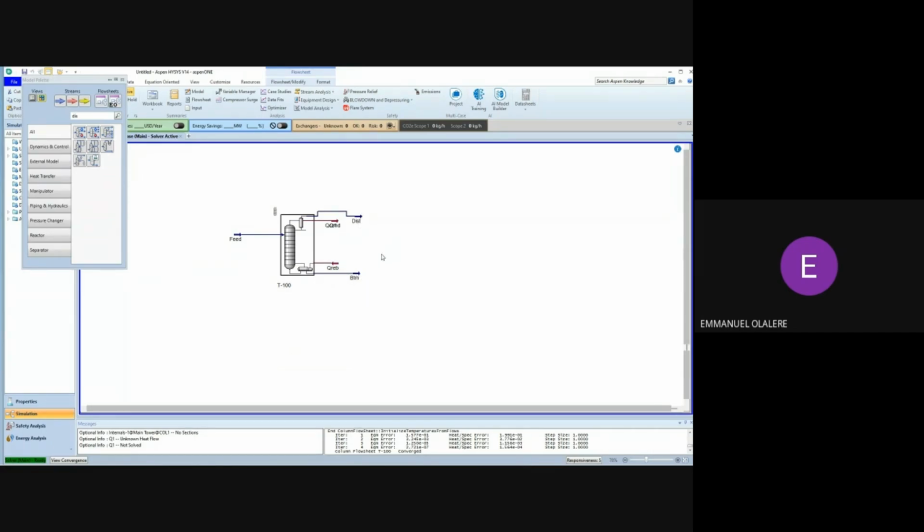So let's say the process is naturally being supplied at 225 degrees Celsius and 250 psi. So I'm assuming that I can't manipulate this. If I can't manipulate the feed, then another thing I can manipulate is the reflux ratio. Now, if I manipulate the reflux ratio, will I be able to obtain the 191 and the 365 distillate and bottoms they require me to obtain? So let's see how it goes.